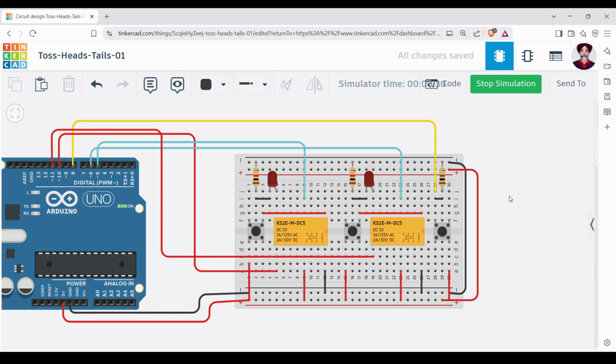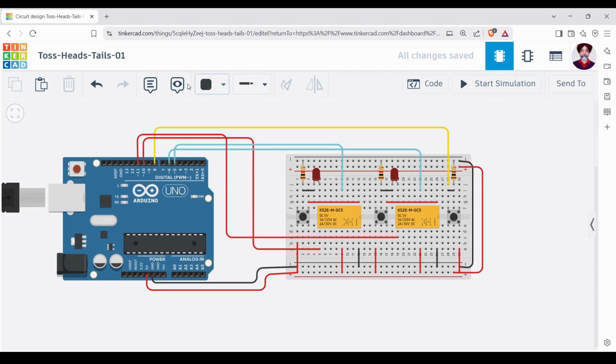All right. Now let's worry about how the feedback from the switches, that is the DPDT basically, is actually reaching the Arduino, and how it is actually going to use it. Let's see, pin number 10 and 11 are going to be used. So let us consider the left one as tails and right one as heads. Let's make a note so that it is tails on this side. If I make a copy of this, it is going to be heads on this side.